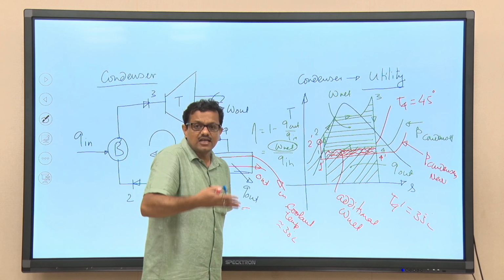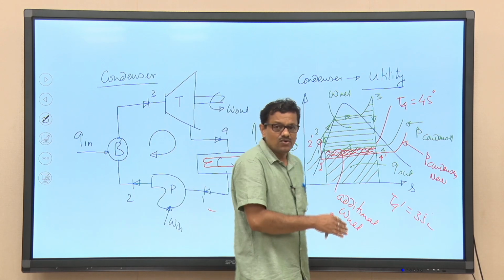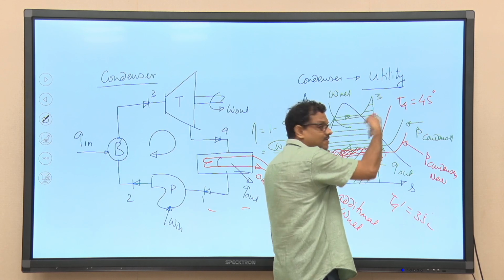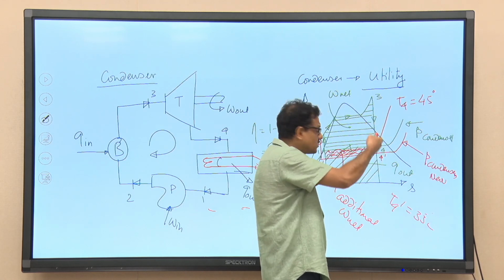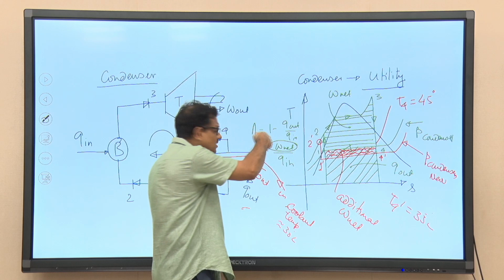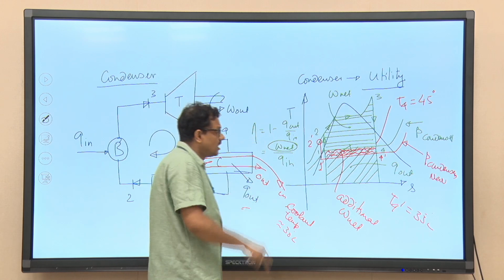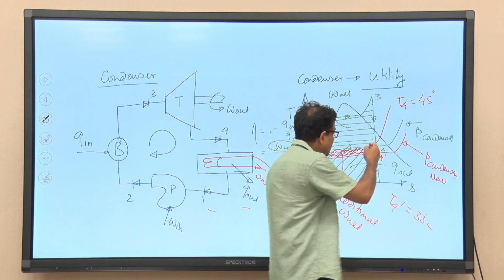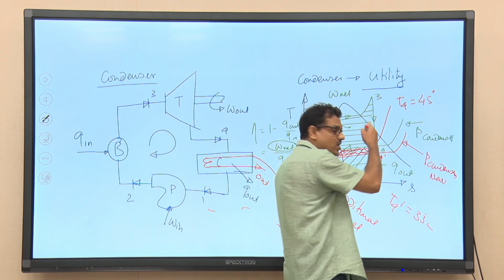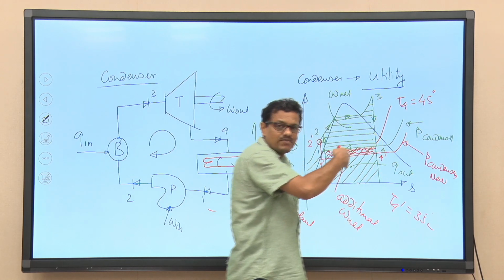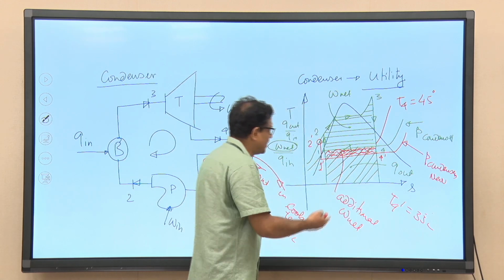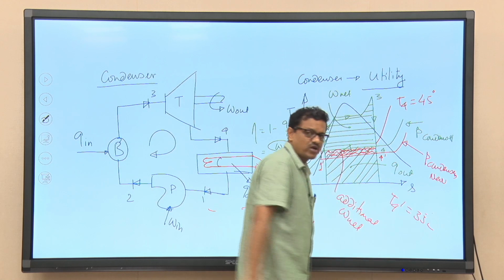So, an air leakage problem would be there. To summarize, we are allowing steam to expand further and further. It is because of this reason that we can have higher thermal efficiency, right. But we are also going to invite one problem: if we allow the steam to expand further in the turbine, the temperature at the exit of the steam will be close to 40 degrees.